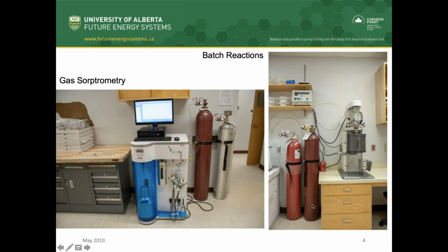And these machines are designed to start to move that into physical and chemical analysis. On the right, we have a machine called a gas sorptometer. This can also confirm the measurements of the porosity, but can also give us information about the nature of the pore spaces themselves, how interconnected the pore spaces are, what the shape of the pore spaces are, are they flat planes, are they big bubbles? And all of this gives us very important information about how fluid will move through a